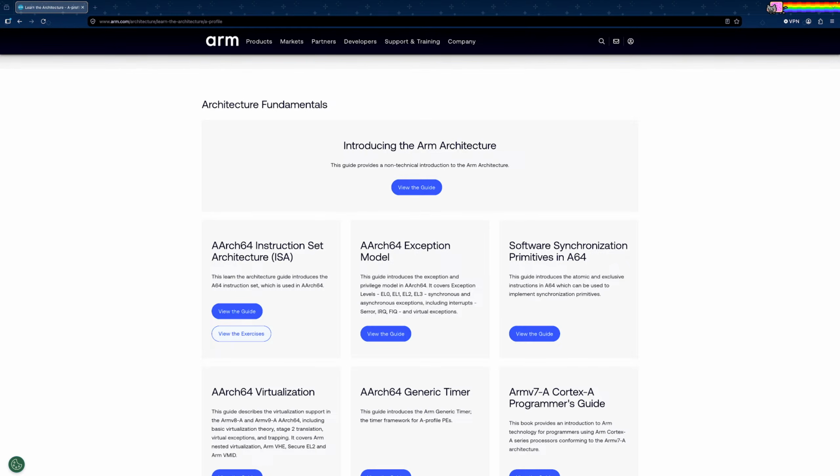We'll begin with the boot process, get code executing at the appropriate exception level, establish a basic runtime environment, and then gradually add support for UART for basic I/O, exception handling, memory management, virtual memory, MMU, and there are many other things that we'll pick up as needed as the project evolves.